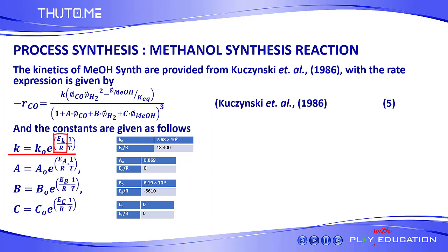And then the reaction kinetics, the way they are, it is the forward reaction and the reverse reaction. If you look at this, the lower part, the denominator, is the adsorption term, which is basically a resistance term, where you have the reactants or the product adsorbing onto the catalyst and not dissolving.